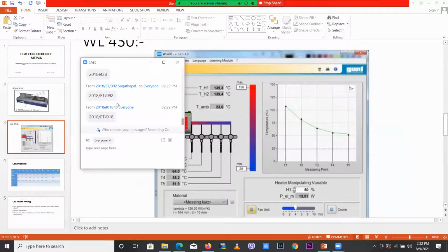We have done this for three different metals: copper, aluminum, brass. But we use the same size metals as samples. We introduce heat on one side, and we measure temperature in 5 different places, and look at which has high thermal conductivity, that means which allows a high flow rate through that metal rod.